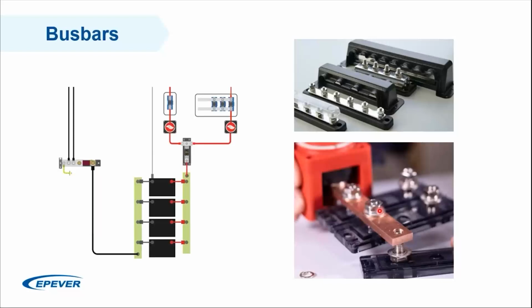Again, for marine applications, you should use tinned copper. And busbars are meant to provide common positive and common negative terminals between the batteries and inverters, chargers, and multiple inverters. They are also used in smaller systems, especially when there is a lot of DC equipment. So if you have DC equipment, you can connect it directly to your battery using these terminals of the busbars.